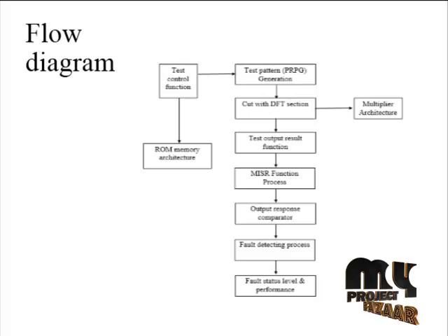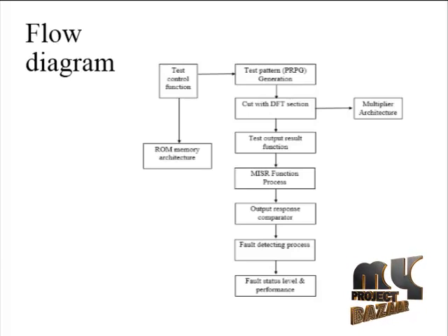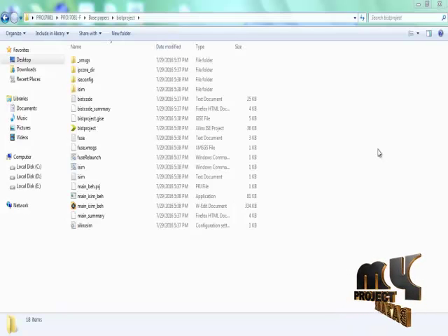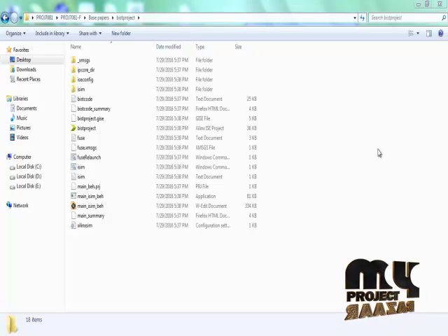The comparator compares the data and the memory. Whenever we give the control signal, the comparator outputs 0 or 1. If the data and the memory are matched, then the output will be 0 because of no errors. If the data and the memory are not matched, then the output will be 1, which indicates an error. Finally, we are going to see the output for our product.